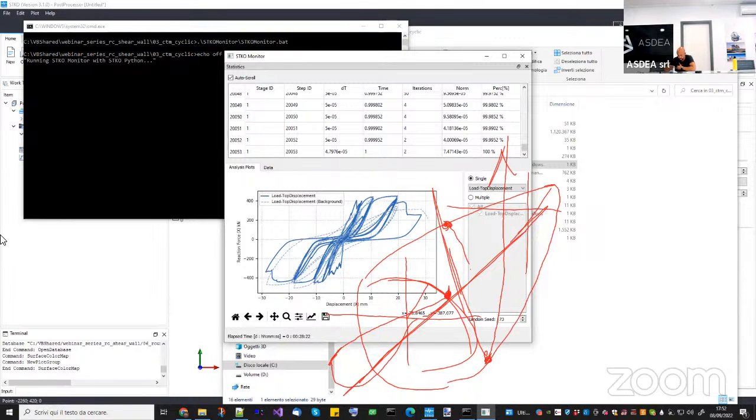But actually, it's very important because what we have seen, for example, if you want to keep this kind of unloading stiffness with a tensorial model, this point here will be hit at this point. And when you reach here, you will see your structure completely damaged.